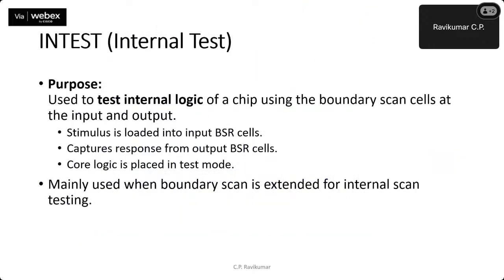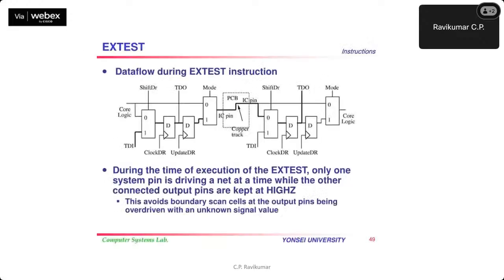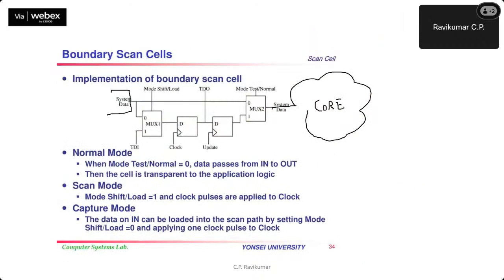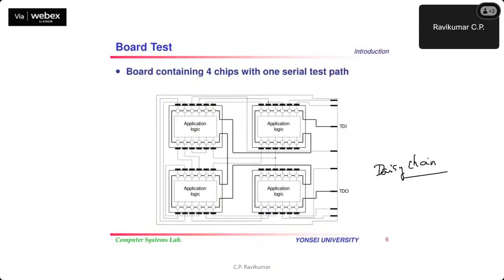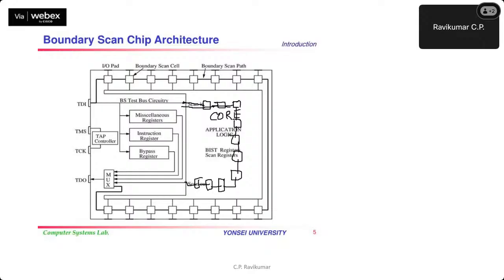Or it could be that this is not possible when we are doing in-field testing, etc. Usually, the customers don't know where the scan chains are. The chip vendor will not explain that these are the scan chains. That information is not given to the customer. The customer may be told about a self test supported in the chip, and the customer will know how to activate the self test.